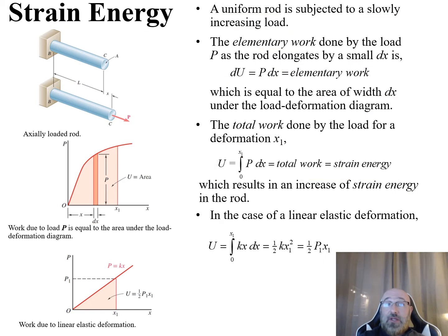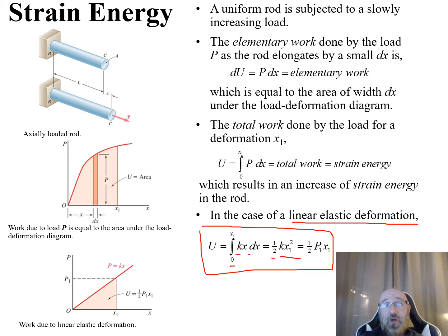So now we want to consider the case for linear elastic deformation. For this, we have the governing equation that we see here, that U is equal to the integral from 0 to x1 of kx dx, which is equal to 1/2 k x1 squared when we do out our integral, which is equal to 1/2 P1 x1.